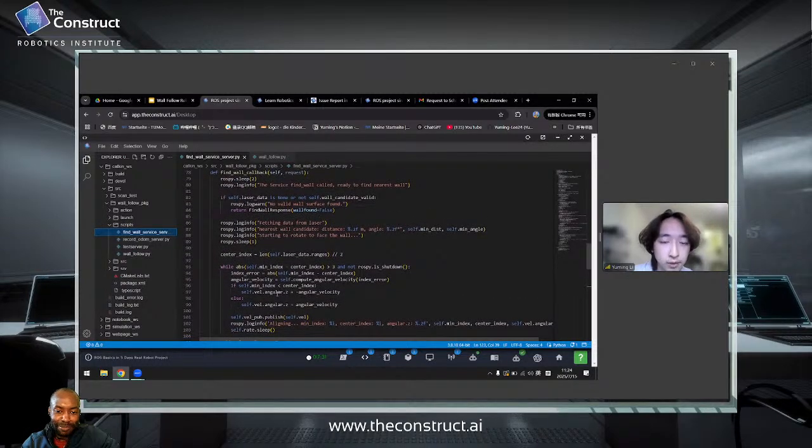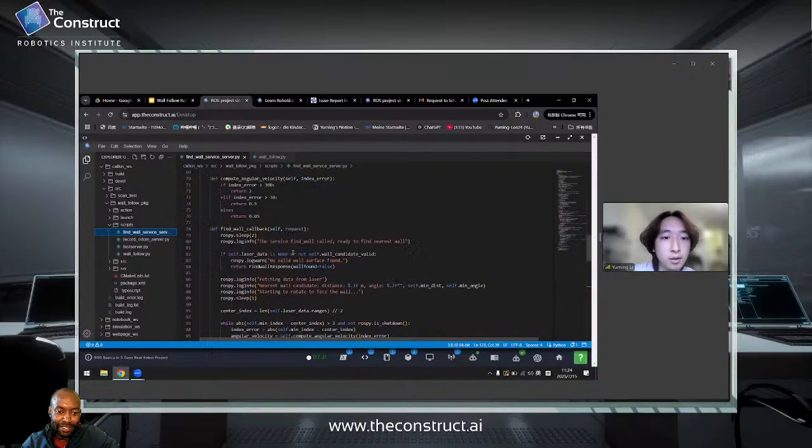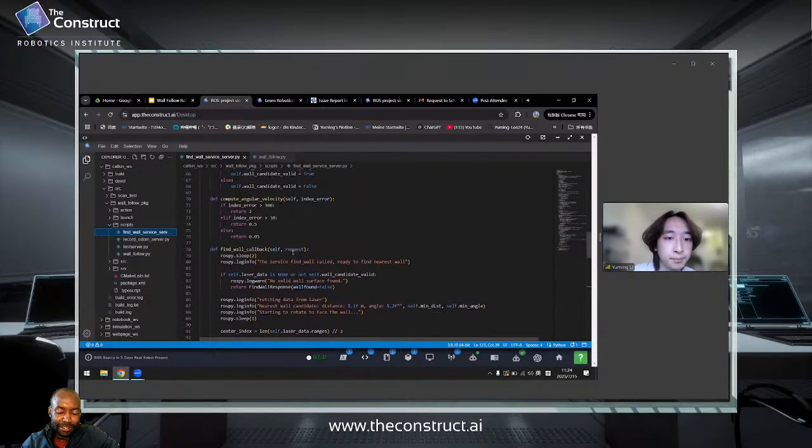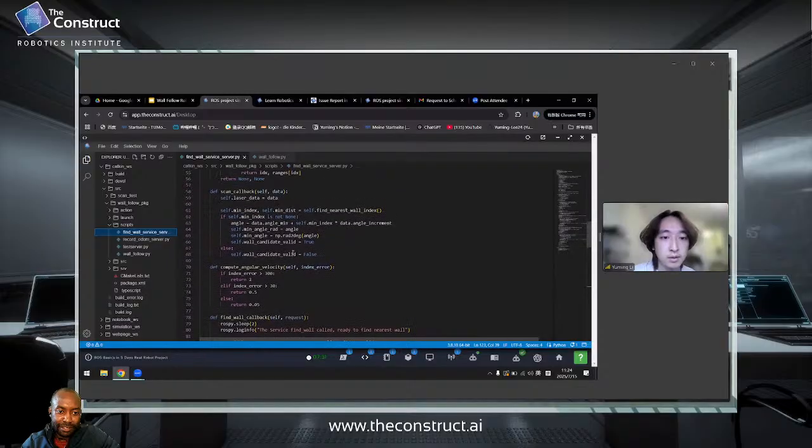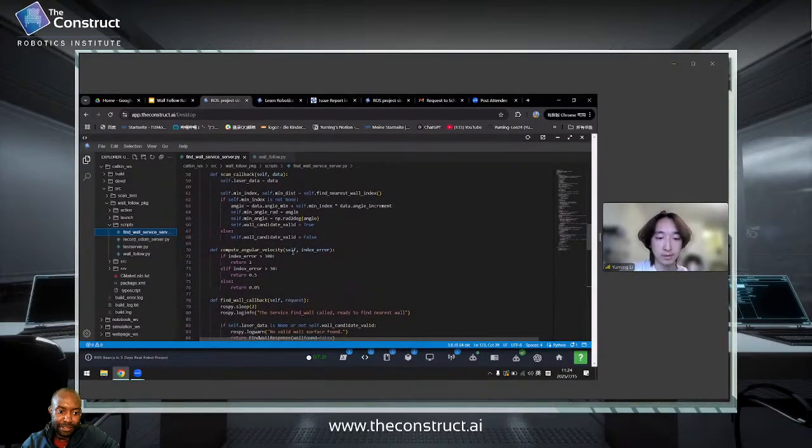Yes, but here, when it's rotating, I let it turn fast when the error is big and turn slower when the error is small, because sometimes it turned too fast and overturned, and it had to adjust and keep vibrating near the target.